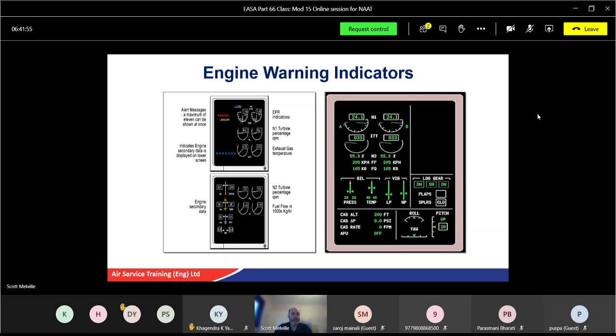When we're averaging temperature readings, some systems will sample temperature readings from the thermocouples at frequent intervals. Fatigue levels, high cycle fatigue or low cycle fatigue, can be determined. Low cycle fatigue. The engine starts, stays on for a while. It's not in and out or off and on like a piston engine.